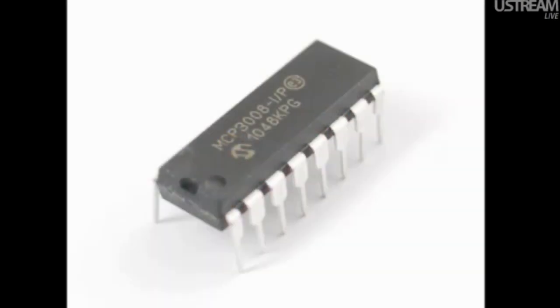All right, and then we've got this new chip that goes along with the project. I also decided to carry the MCP3008, which is a low-cost DIP, 8-channel analog input converter chip. The Raspberry Pi does not have analog inputs. However, it does have plenty of GPIO, SPI, and I2C, and this is a chip that's really easy to bitbang SPI with. It works down at 3 volts, which is what the Raspberry Pi runs off of, and it has 8 channels, and it can do them really fast.